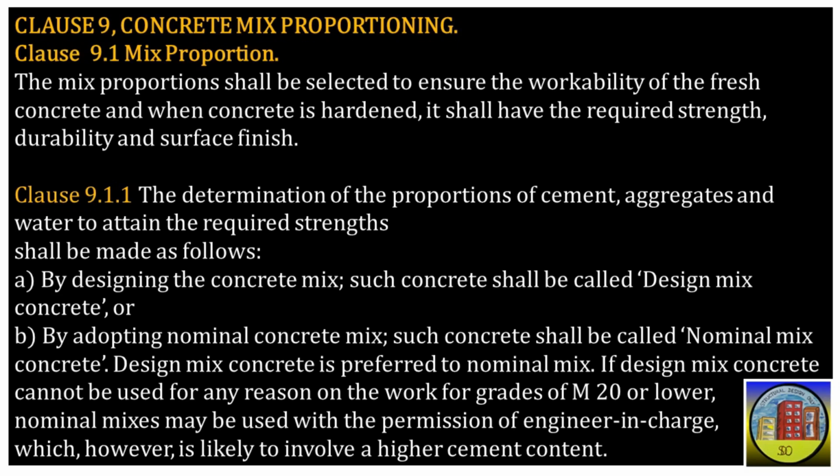Design mix concrete: scientifically calculated mix to achieve specific strength, durability, and workability for your project. We may call it tailor-made recipe. And nominal mix concrete: fixed ratio of ingredients based on experience, suitable for lower grade concrete, M20 or lower, when design mix isn't feasible. We may call it predetermined recipe.